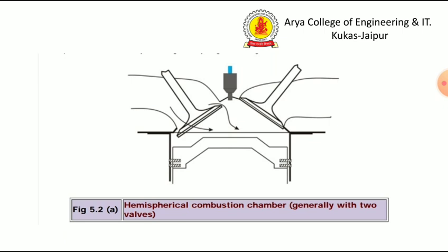Both the intake and exhaust valves are inclined, increasing valve port area that results in high volumetric efficiency. The chamber also has a low surface to volume ratio. The intake ports are provided with a suitable curved geometry to generate a high rate of air swirl, and the small cylinder engines can be operated at higher speeds with increased turbulence, which tends to reduce HC emissions.